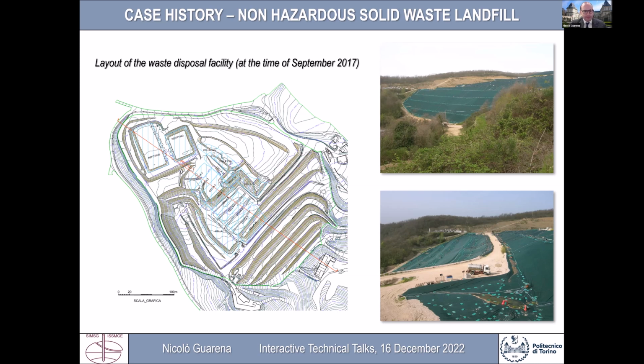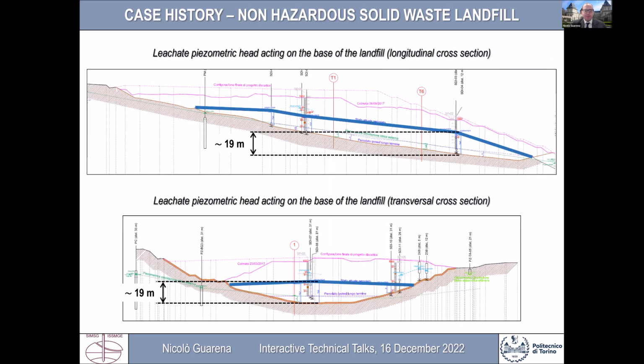A series of piezometers was also installed, thereby allowing the piezometric surface within the waste field to be reconstructed. Such a piezometric surface was associated with an excessive leachate head acting on the base of the landfill, as high as approximately 19 meters in some areas of the facility, which was clearly unacceptable not only from the viewpoint of the geotechnical stability, but also from the viewpoint of the release of contaminated liquids into the surrounding environment.